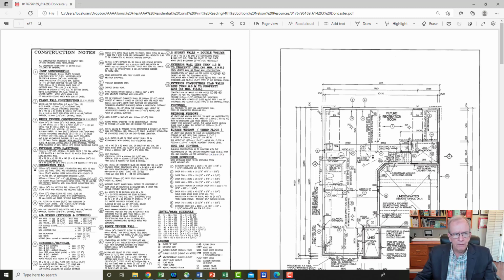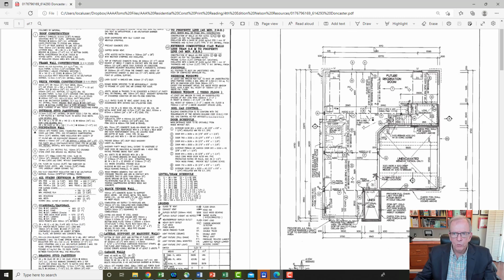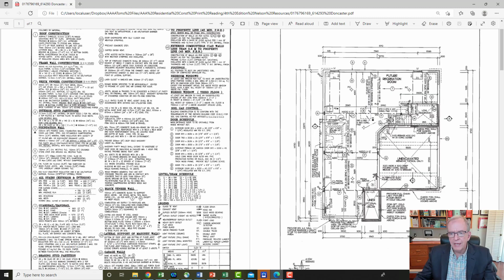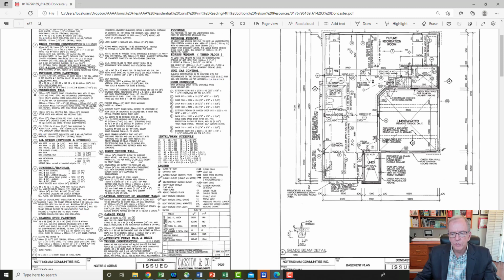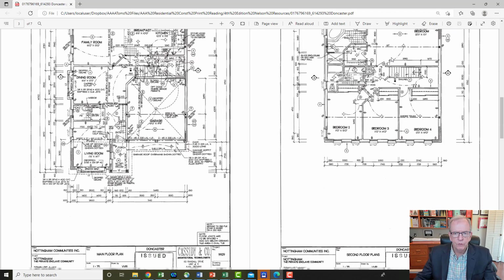And they have a lot of detailed information that you actually don't want to put on things like the floor plans over here. You want the floor plans to be readable. You want to have basically extension lines and dimension lines that you can size things out on. And we basically start out with the basement plan in these particular drawings. So pretty much in this set of drawings, they go with the floor plans, basement floor plan, and then you got first floor plan, second floor plan.